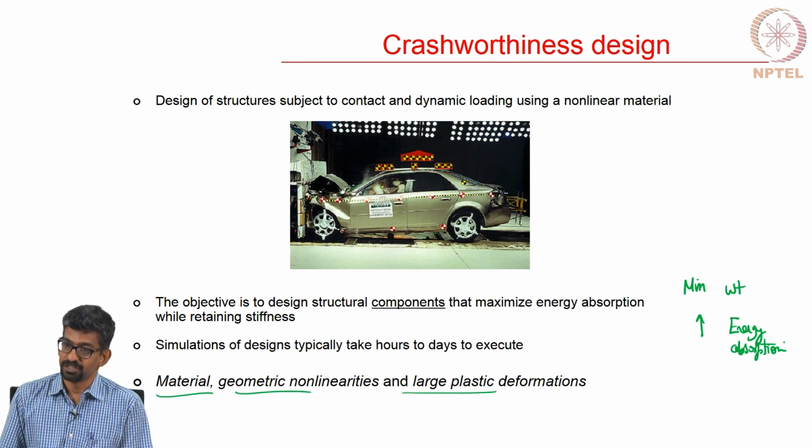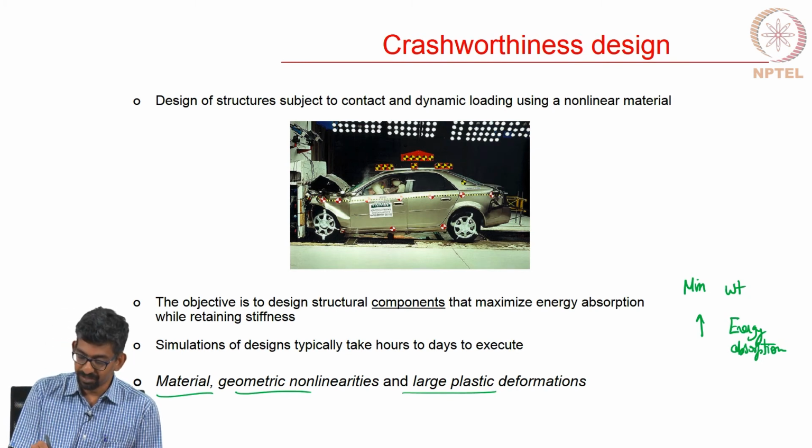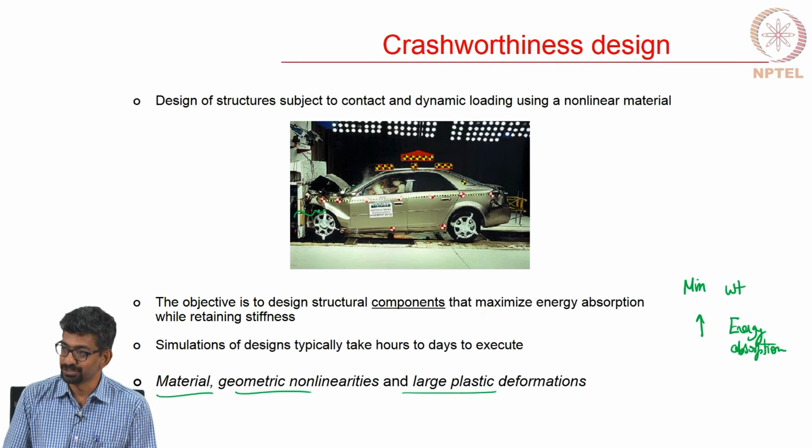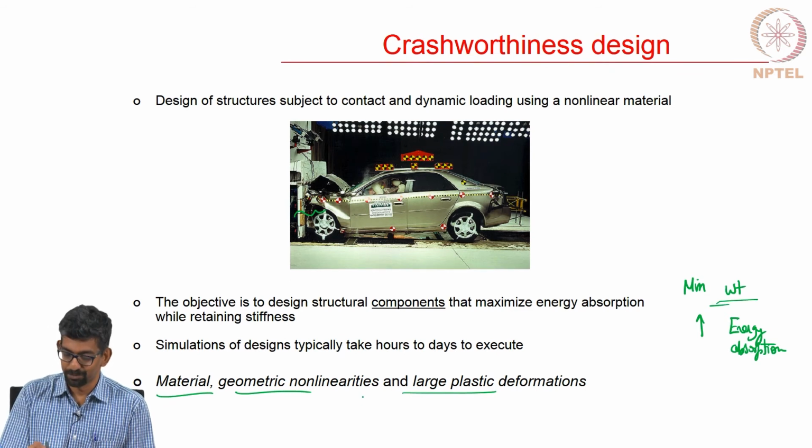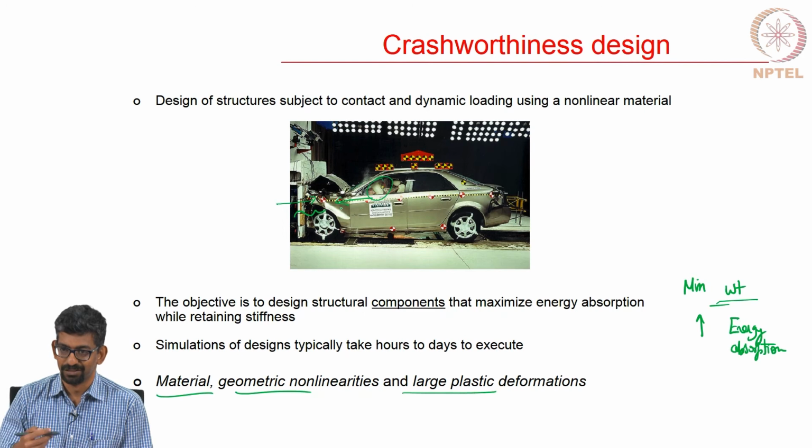And even in energy absorption, only in the frontal part you want to increase the energy absorption, because if you want to do energy absorption, I can put a concrete. Of course, my weight will get affected, but I can put a concrete in the front, it will absorb all the energy, it will not send it to the dummy or the passenger. But there is a problem, because crash propagates this way and our inertia propagates this way. So, you will go and bang on the concrete.